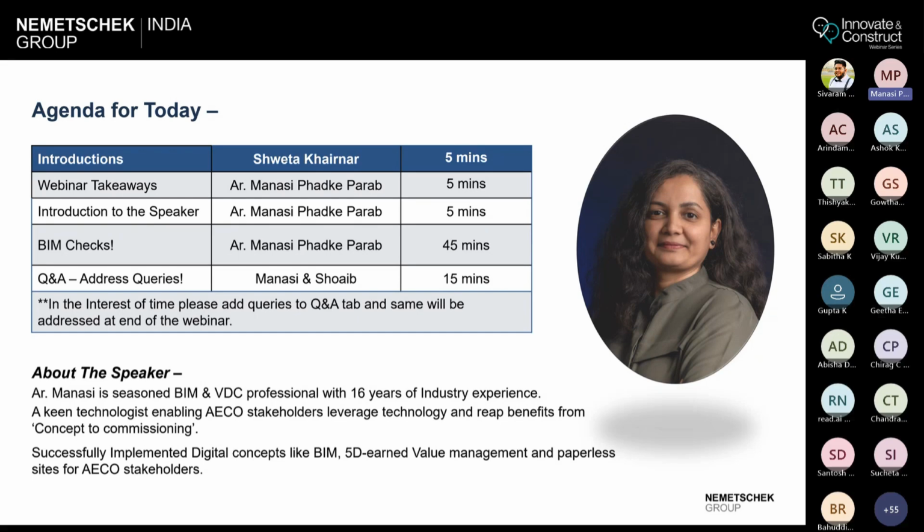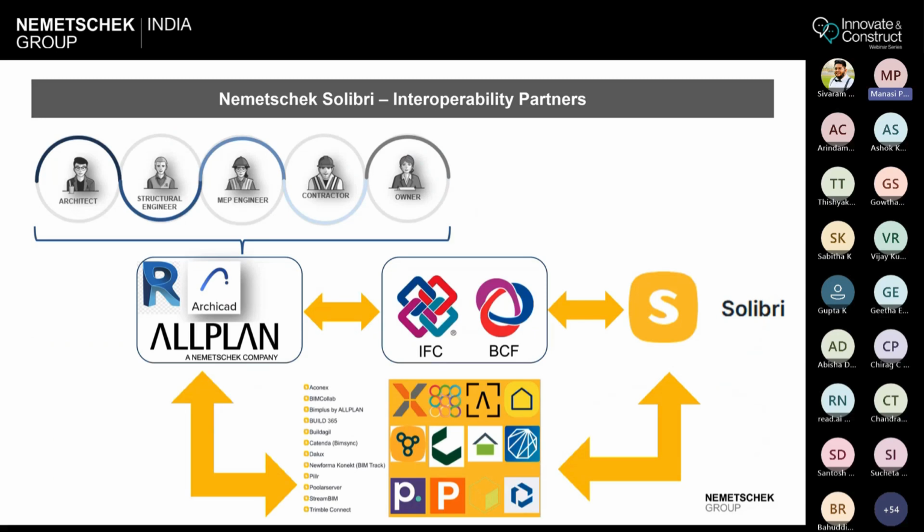So let's deep dive more. And before deep diving, let's understand the workflow, what Solibri exactly is, whom it is for. So talking of interoperability partners of Solibri, or how many tools Solibri can integrate or talk to today. The only input Solibri takes is the IFC file format, and the issue management output or input or coordination file format Solibri understands is BCF, which is a global file format.